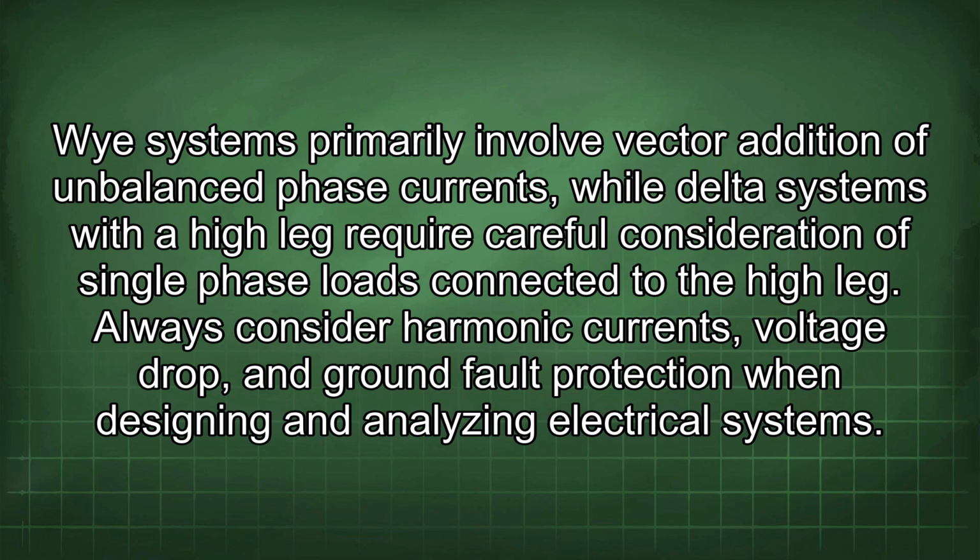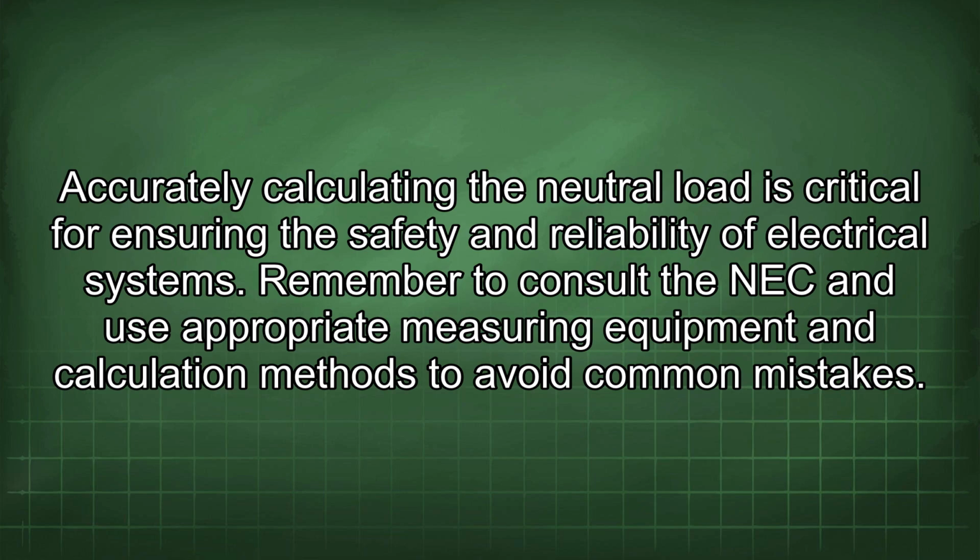Always consider harmonic currents, voltage drop, and ground fault protection when designing and analyzing electrical systems. Accurately calculating the neutral load is critical for ensuring the safety and reliability of electrical systems. Remember to consult the NEC and use appropriate measuring equipment and calculation methods to avoid common mistakes.